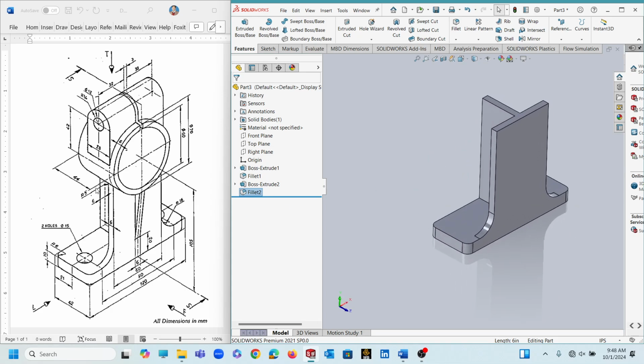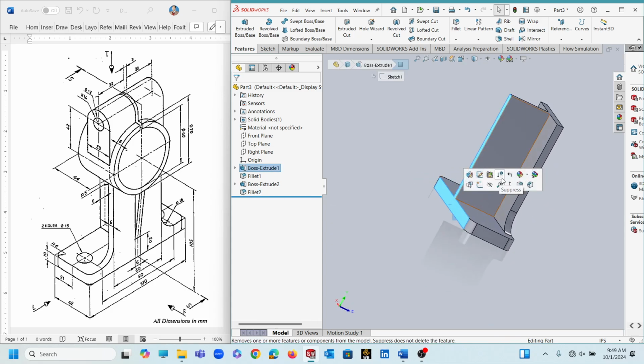So then we need this circular protrusion, this one. This total protrusion is of 44 unit, while the width of our base is of 42 units. So it means the circular protrusion is 2 units more as compared to base. So where this excessive portion would be, on what side? It would be in the front side, because this rib indicates this is somewhat excessive portion of the circular protrusion. So we will start from the back side. So you will choose this face, go normal to it